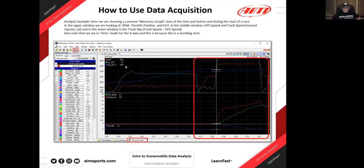And in this case, we've got throttle position up here. It's at 67%. It's this blue line. All of these are changeable in color if we wanted to, but that's the blue line. You can see this is the start of the race. He's sitting here, the EGT is coming up as it's going up there. That's the blue one. And then he releases the throttle a little bit, RPM was starting to come up just a little bit. And then right here is where the rider went to full throttle. The RPM starts coming up.